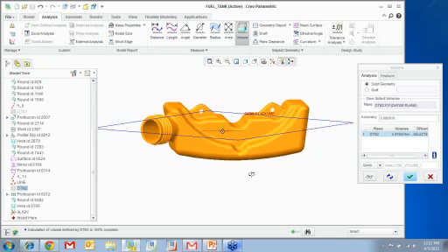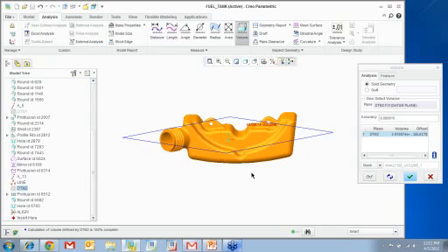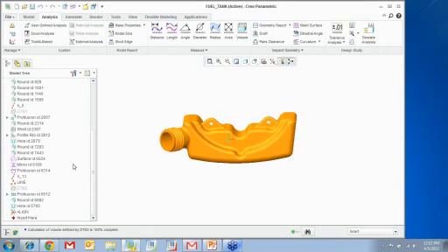Now, where can we use this? We can choose to minimize or maximize this volume by moving this plane up or down. So in this way, you can get a marker for, say, half the tank or 3/4 the tank or quarter the tank, right? So you can move this plane and measure out what level is half of the volume or quarter of the volume. So here's an example for one-sided volume.